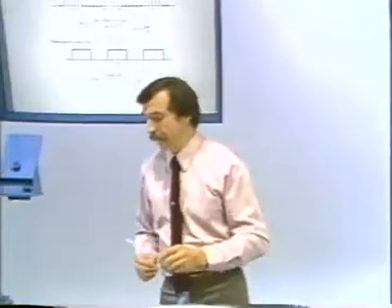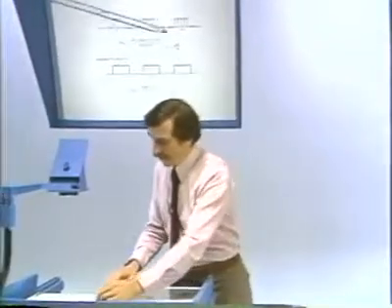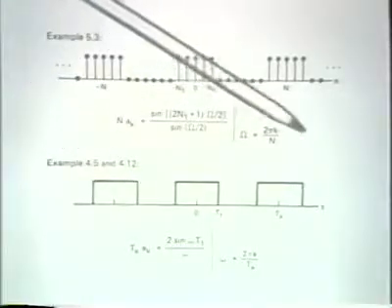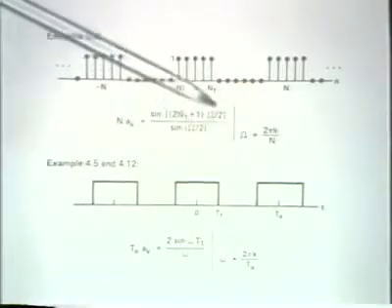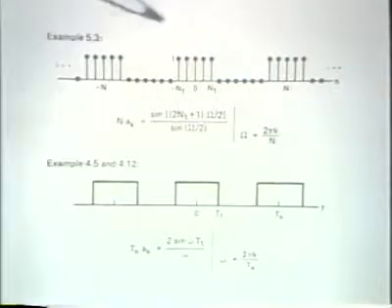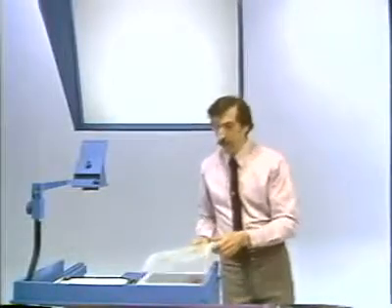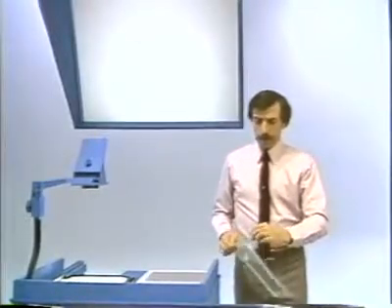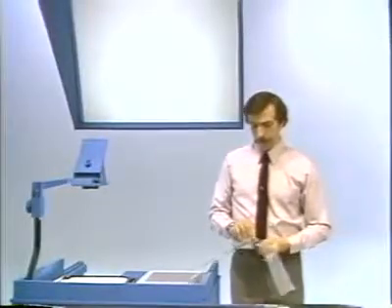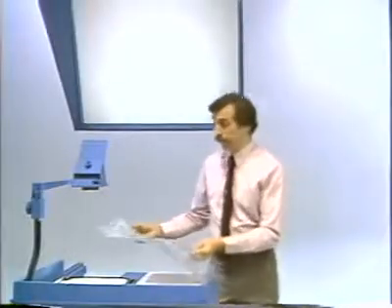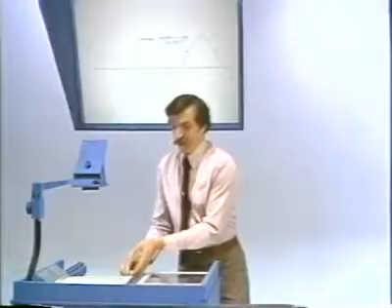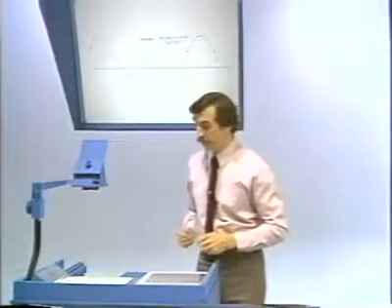So once again, if we look back at the algebraic expression, it's samples of the sine nx over sine x function that represent the Fourier series coefficients of this periodic square wave. In the continuous time case, we used the concept of an envelope to represent the Fourier series coefficients, the notion that they were samples of an envelope, and that is the same notion that we'll be using in discrete time.